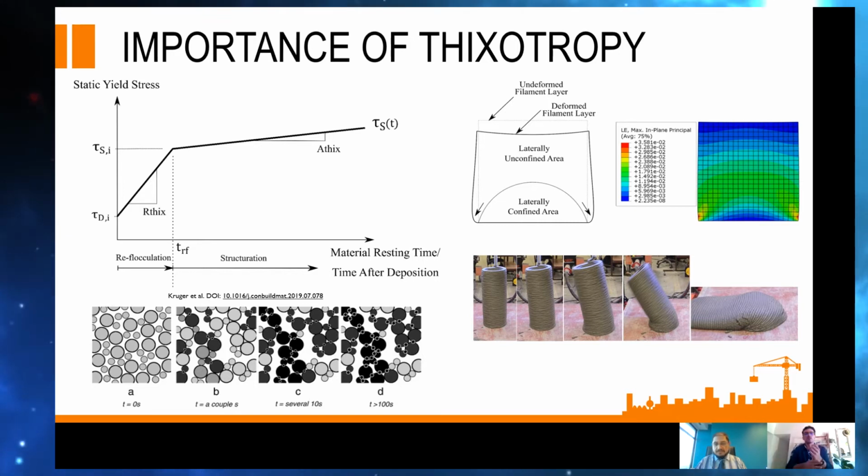So we have this trade-off, we call it a physico-chemical response. We have a certain component that's physical and reversible, and a certain component that is irreversible and chemical by nature. So meaning essentially, from a layman's point of view, once the cement has started setting, it's setting, and you can't reverse that. Would I be correct in my assumption? Absolutely, there's a certain component which you cannot reverse over the longer time frame, but within the short-term time frame, there is a reversible component.